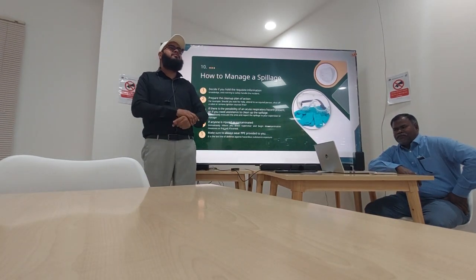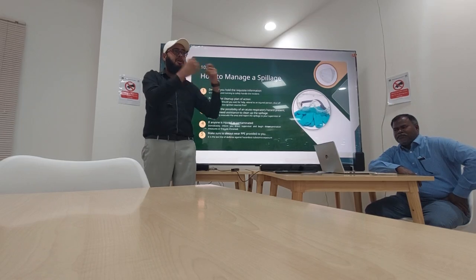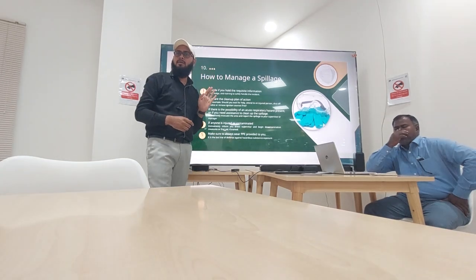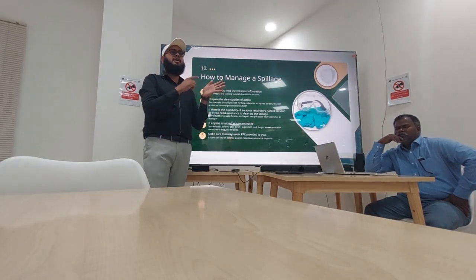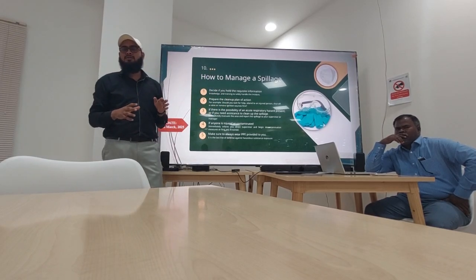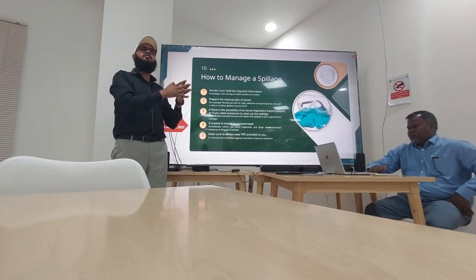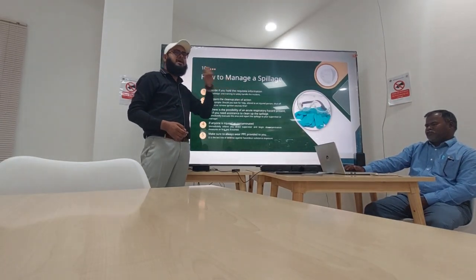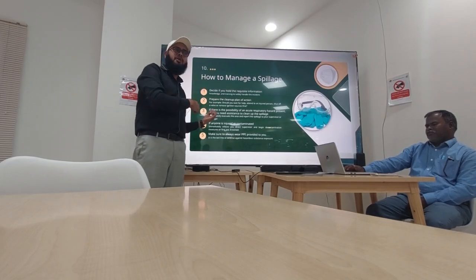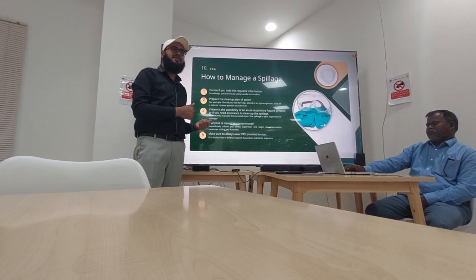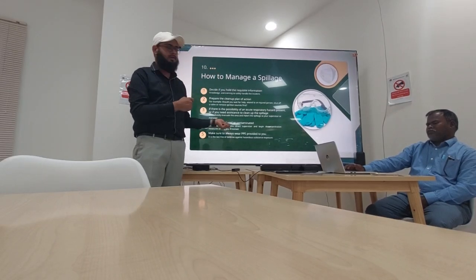So wherever this happens, even a trained person will go and first review the MSDS, because the MSDS gives information on what type of chemical it is, what its composition is, and what the temperature is. Everything is there. So he will obviously review the MSDS and prepare the cleanup plan of action. The one who is trained will go and see the situation. He will first review and check the MSDS and respond accordingly.